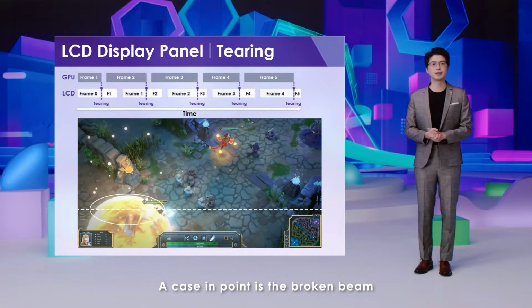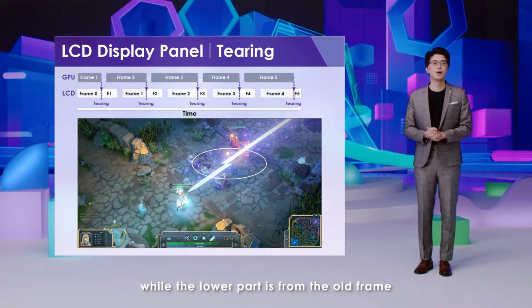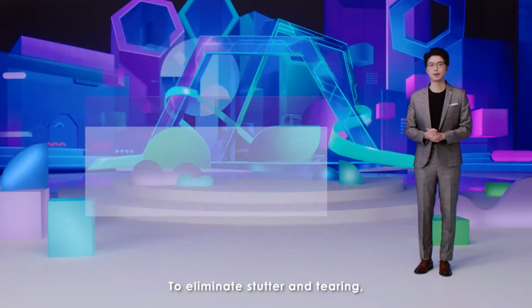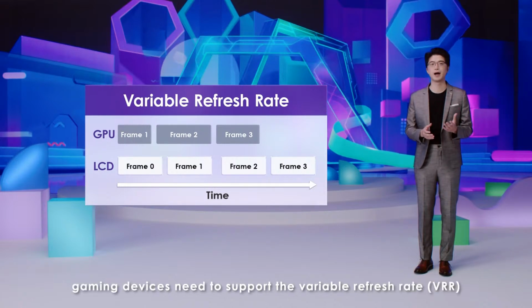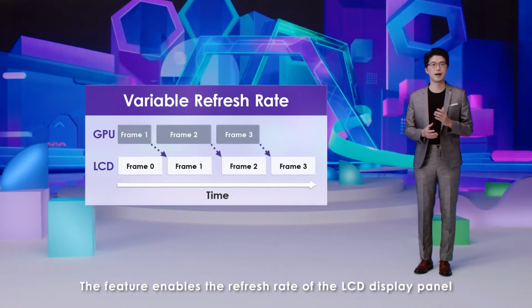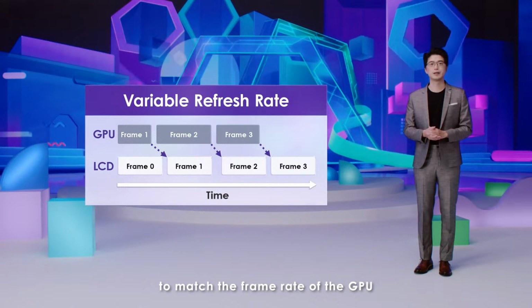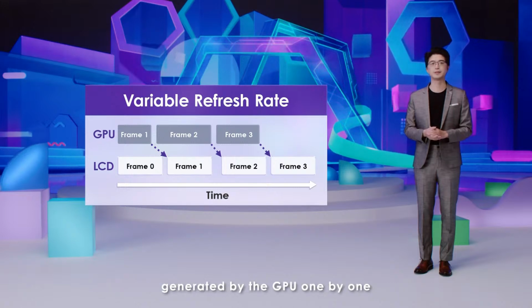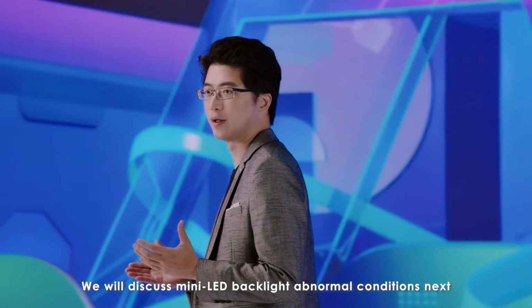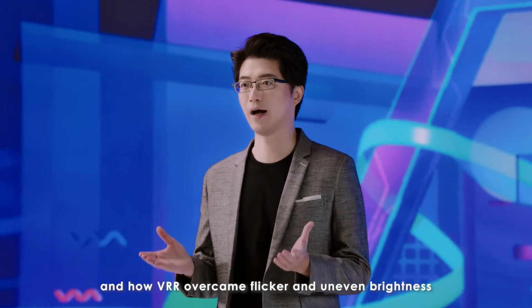A case in point is the broken beam, as the upper half of the image is from the new frame, while the lower part is from the old frame. To eliminate stutter and tearing, gaming devices need to support the variable refresh rate, VRR. The feature enables the refresh rate of the LCD display panel to match the frame rate of the GPU. As dynamic sync is achieved, the LCD display panel will be able to show every frame generated by the GPU one by one. We will discuss mini LED backlight abnormal conditions next, and how VRR overcame flicker and uneven brightness.